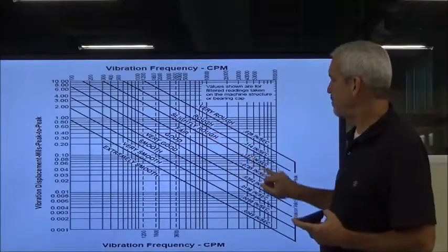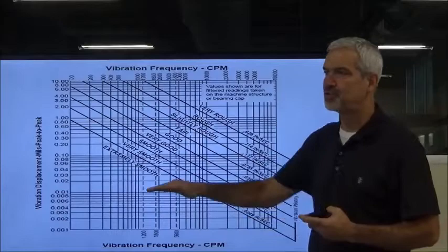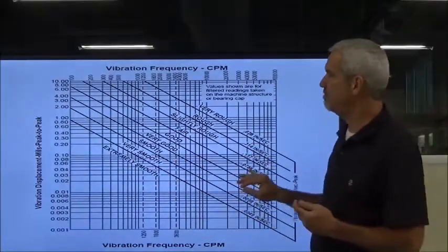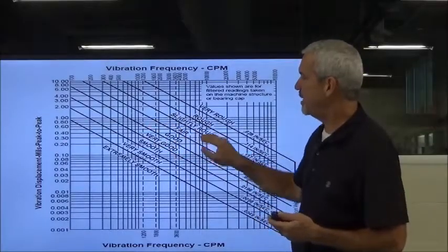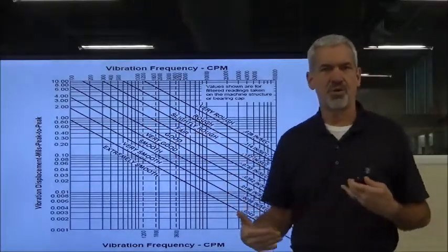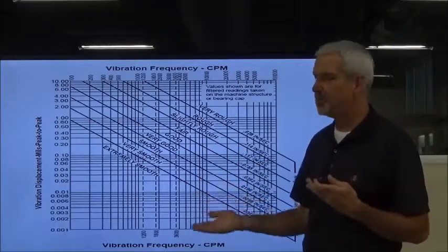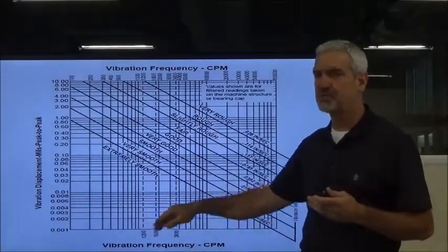And then we convert this to inches per second. That's how far it would travel if we were to put it in a linear path. But this chart, and again, we'll go over this more in lab, gives us an idea: is the bearing smooth or is it rough? Is the vibration and that displacement considered rough, very rough, extremely smooth, very smooth?